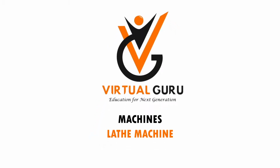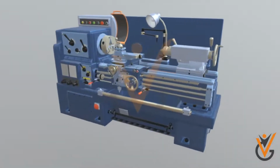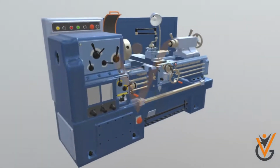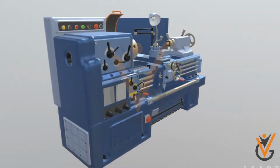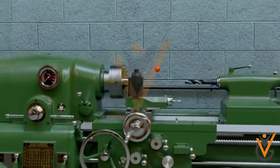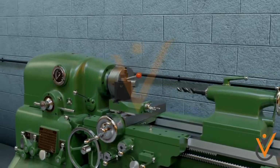Machines. Lathe machine. Lathes are one of the most versatile machine tools in the industry, used to perform a variety of machining operations. The lathe is applied to the tool and rotated to perform various operations. It can be used for facing, turning, knurling, grooving, drilling, reaming, boring, cutting or parting off.